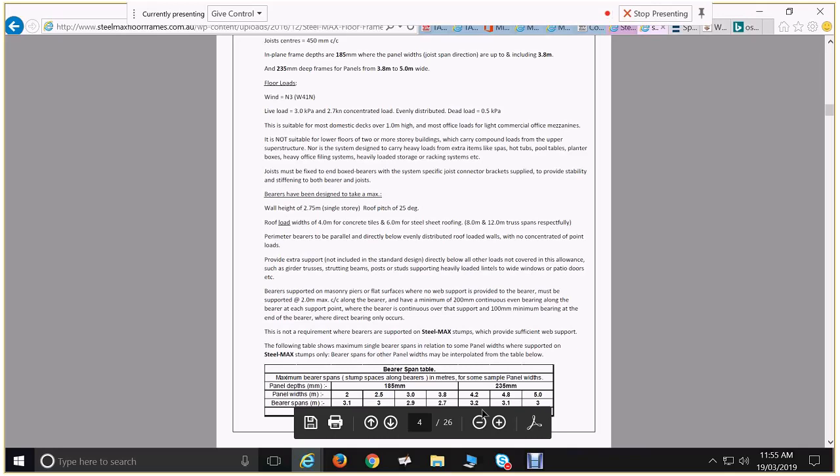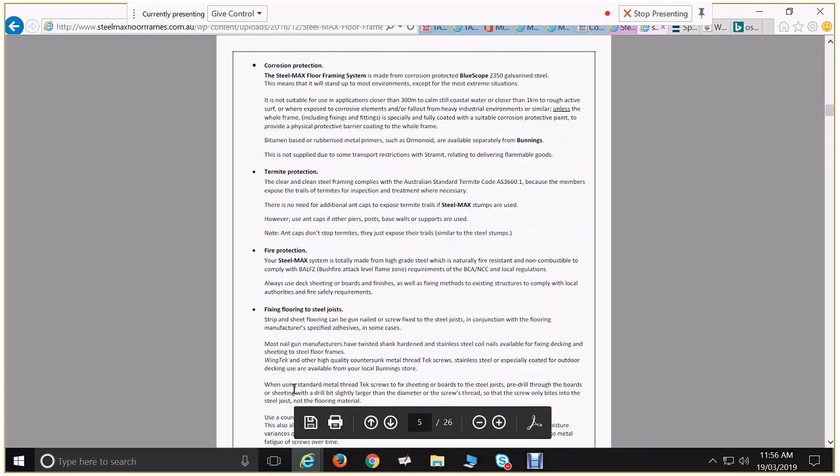Now, as you go along, as drafters and designers, you'll get a bit of a working knowledge of the cost of various different aspects. That's something that you really have to do yourself. There's programs like Cordell's and whatever that help you with that a lot. But eventually you'll come to a point where you go, okay, well, a pier in this situation is going to cost me about $150 per pier. You go, all right, if I do this, well then sum them all up, that's what that one's going to cost. Or if I go this other solution where I'm spending a little bit more on the framing, but I'm saving on piers, it's going to save me this much money. So it's all going to be that sort of interaction. But you've got the bulk of your information you'd be needing to make those decisions within these various different design guides.